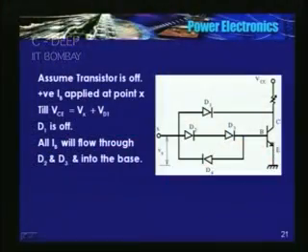But then VCE in this circuit cannot fall below a value equal to Vx minus Vd1. In this circuit, at any given time VCE is clamped at Vx minus Vd1. So even if the load has come down, the same IB will not flow.